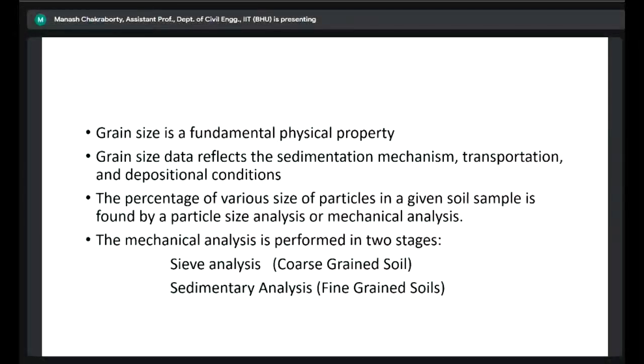Now, if I take, let's say, 500 grams of sample, wherever I perform this experiment, whether in Kashmir or Kanyakumari, you will have the same grain size distribution curve, right? This statement cannot be made for other properties, and that's the reason the grain size distribution curve makes so much sense, right? It doesn't depend on your environmental aspects. In a sense it's a fundamental, or if I have to use the word, intrinsic soil property.